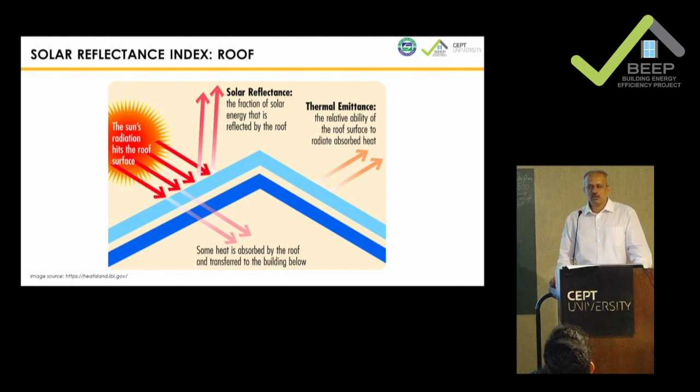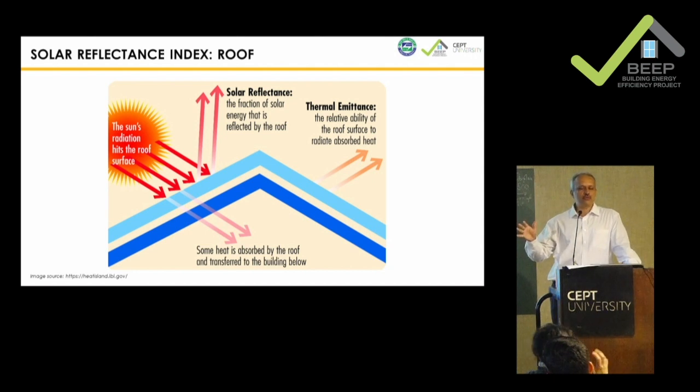What we talked about is all wall. Now very quickly, on a roof. All those things which work on a wall also work on a roof, but one more additional. So roof U value or roof R value is important because R and U value deals with the conduction side.